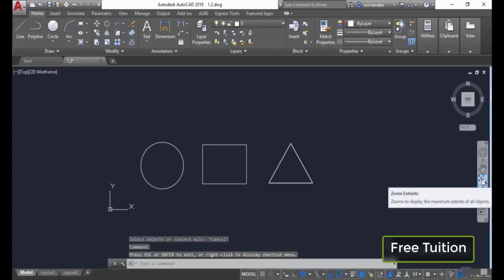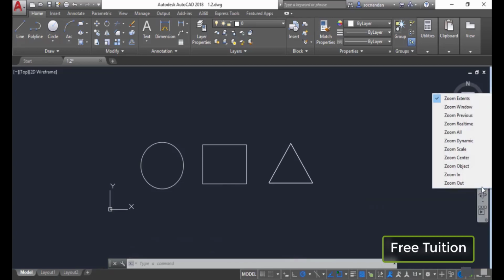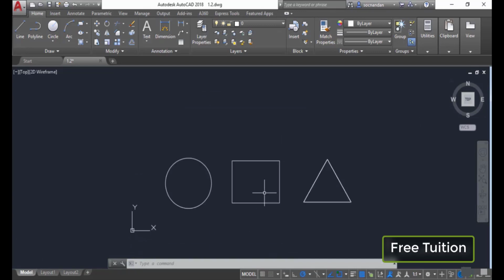In order to use the zoom tools, simply select this small arrow right under the zoom extents tool, and we have multiple options for zoom. You can select any of these options. For example, the zoom extents is selected as default. If you select zoom extents, the drawing will fit completely in the area provided. Wherever our drawing is, it hardly matters. When you select zoom extents, it will fit in the provided space.